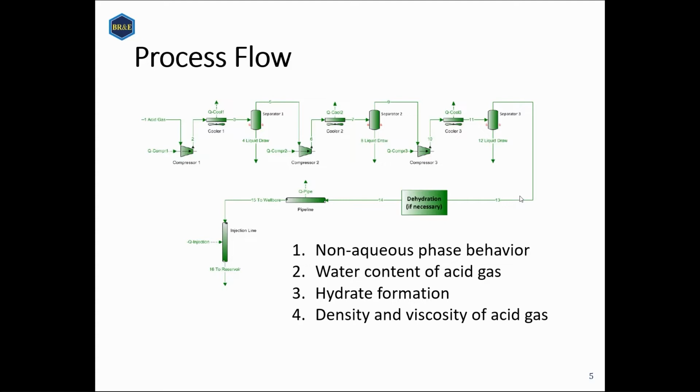So when it sees that amine unit again, it's going to be a little bit richer in acid gas, and it's possible it will overload that system over time. Because we're dealing with these high pressure acid gases as well, we're going to be using pretty much all stainless steel in this compression system that protects the equipment from corrosion